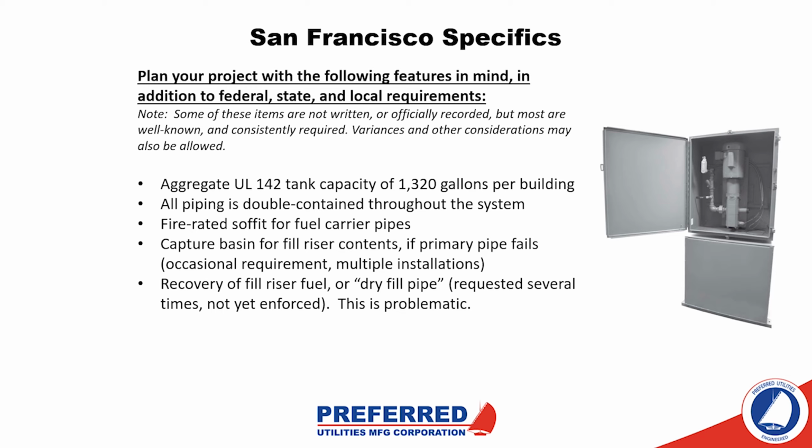So there are a few more San Francisco specifics that we want to go over real quick. Again, these are things that we've encountered but aren't necessarily required on every single project. But these are actually quite common on this particular slide. So the first one being aggregate UL 142 tank capacity of 1320 gallons per building, and that is an aggregate